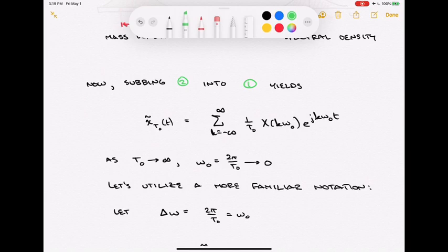I can synthesize my waveform x tilde sub t naught of t as a sum of weighted basis functions. Our basis functions are those harmonically related exponentials. It's just that now, instead of the x tildes, we're putting in sampled and scaled versions of that underlying continuous density function, x of omega.